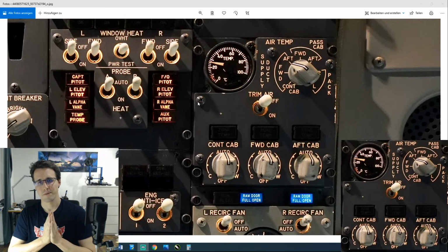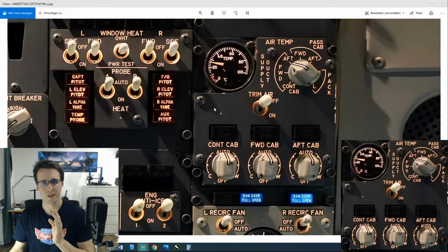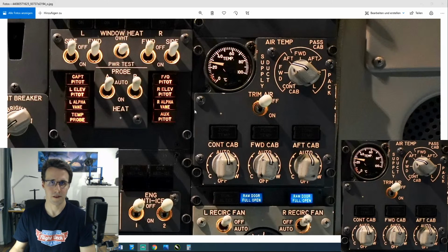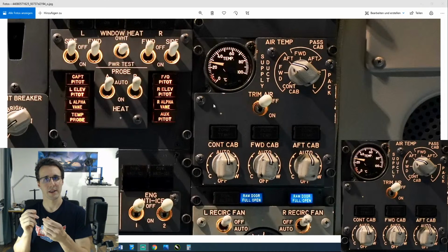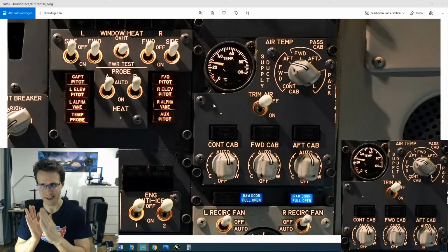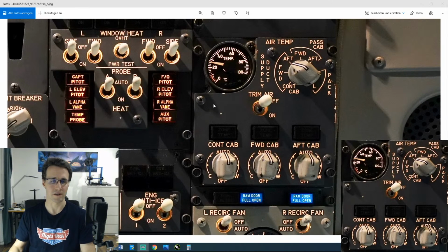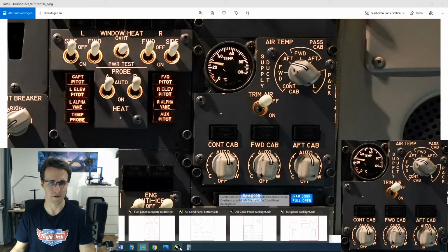I bring them to 60mm from the outside here, and there I have the space where I drill through all the 3 panels. They are connected, and behind this there comes this 50mm hex standoff, and onto this hex standoff the backlighting panel will be mounted later, and so it won't collide with any other hardware.